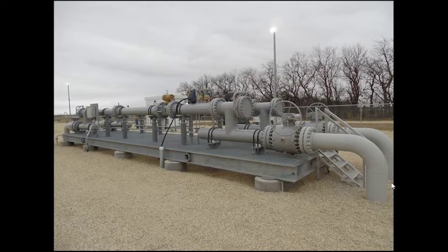And if you're going to build a facility this way, you want to take this entire assembly from this flange at this point to this flange down here and run this in the flow lab and flow calibrate that whole assembly, accounting for the distortions you're getting at these points. The thing you're not accounting for, though, is what happens with the rest of the piping. You've got an elbow going down here.